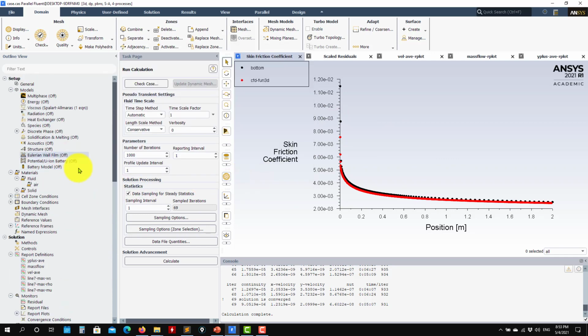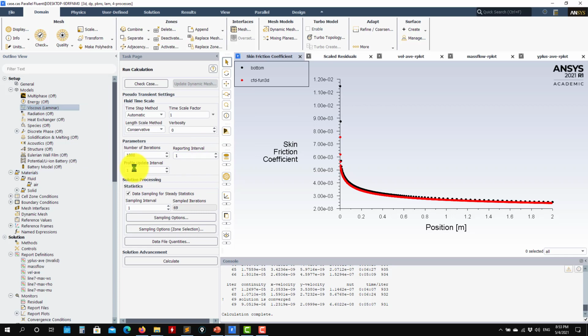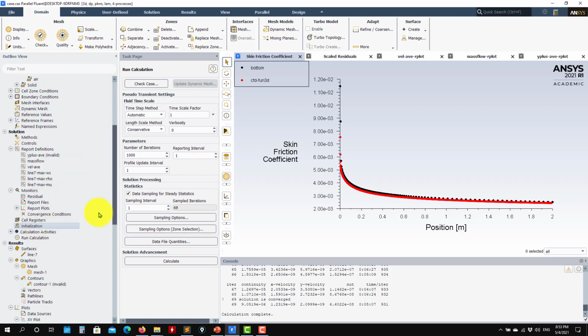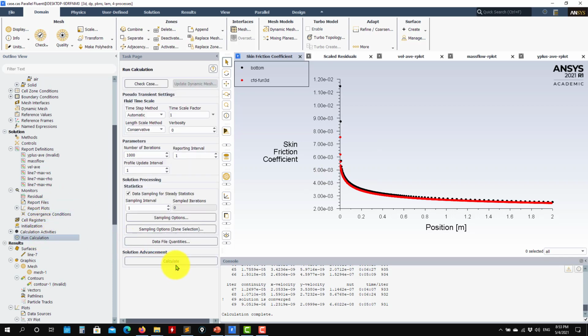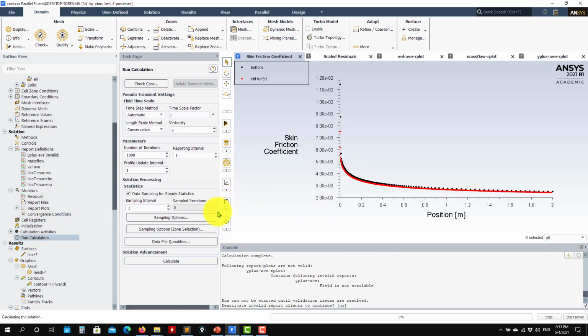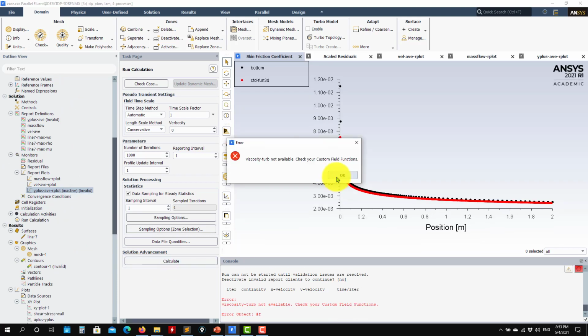And just to convince you of the importance of turbulence modeling in CFD, let me go back here and choose laminar. If I choose a laminar model, I shouldn't get good results because this mesh is not good enough to resolve all these scales. And even something that seems very trivial here, it's telling me that y plus is not computed, so let me deactivate this, because the y plus is not computed in laminar. I know why the guy from Fluent didn't put it, so you need to deactivate it.